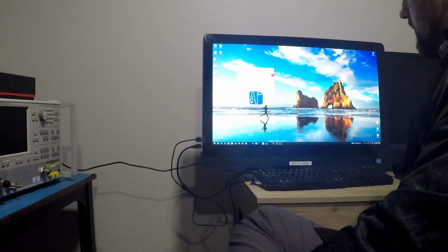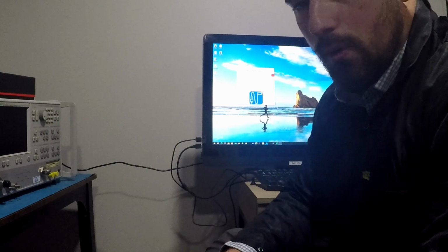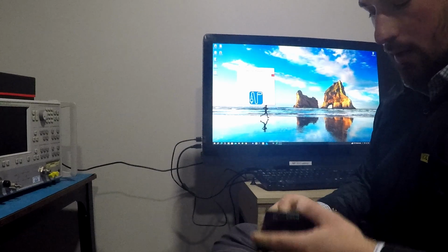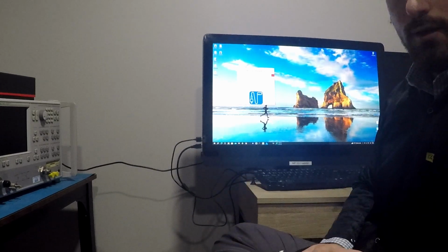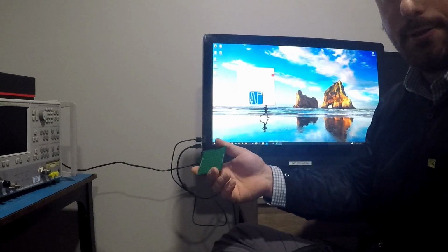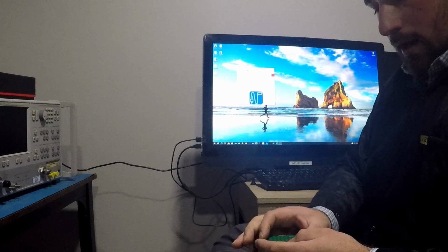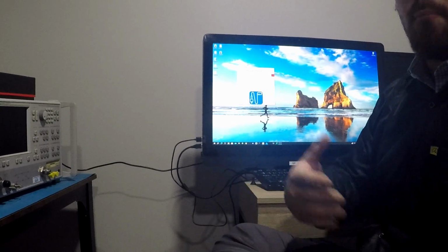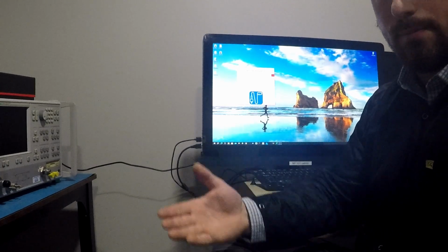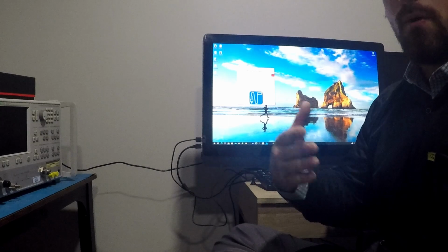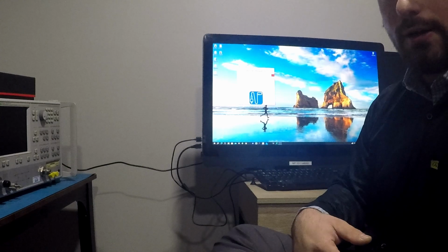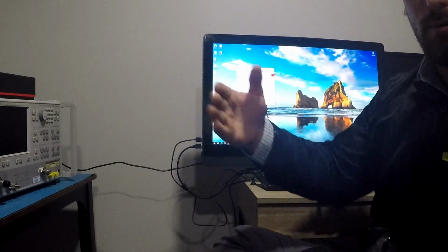The antenna was designed in a 6-layer board. What you're going to see is each individual layer created on a separate board. We have the main logic board, the DC board, and then the antenna board, which is created on some Rogers material. It was really expensive and really slow to get mixed-material prototypes made with Rogers material. It wasn't really practical, so I went about designing 3 separate boards that we just wire together.